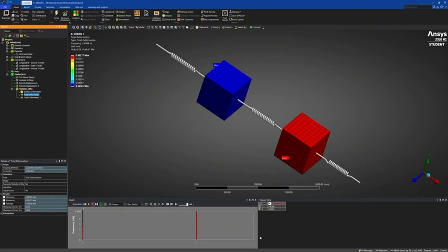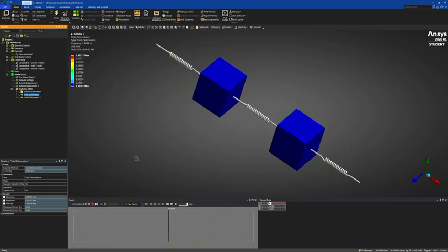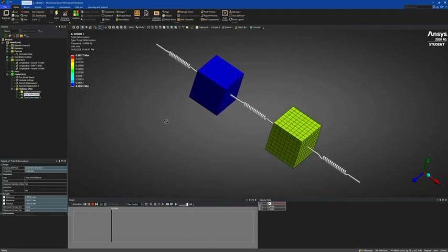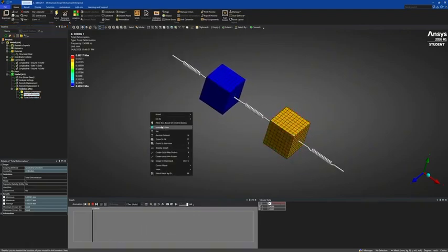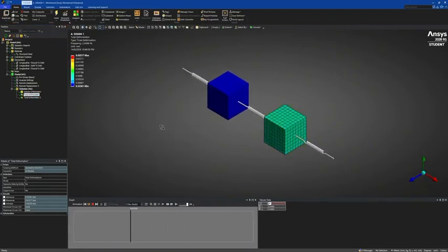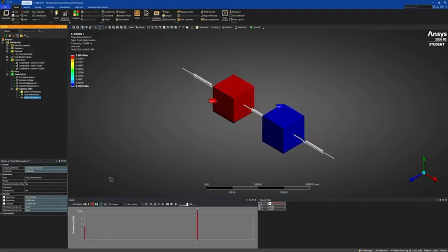For design 1, the first answer is 2.4388. Second is 5.3993. And to get the mode shape, we must divide M2 over M1, so we get a positive value, because as you see, it moves in the same direction for mode shape 1. So for mode shape 2, we get a negative value because they go in opposite directions.